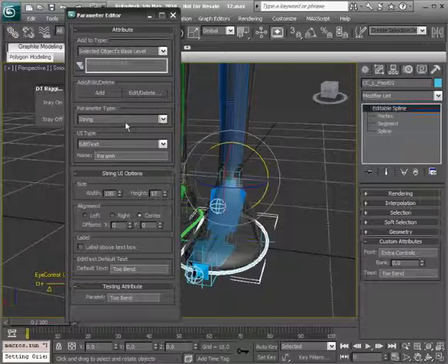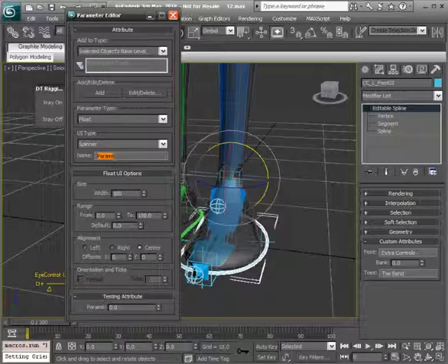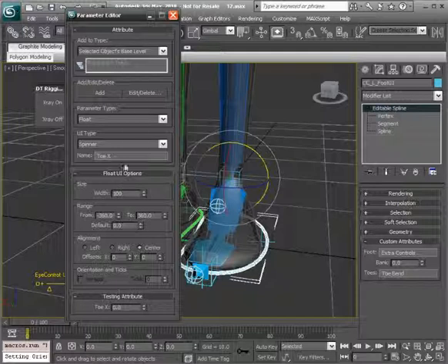Okay, now that that's done, we'll go back to our parameter type, use float. The first control is going to be for the X direction for the toe, so we'll simply label this toe X. We don't have to have a huge range for our from and to, or for our min and max. So for the from, I'm going to just put in -360. For the to, +360. The width we could also change to 100, what we've been using before, and then choose add.